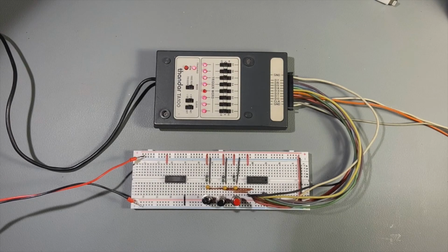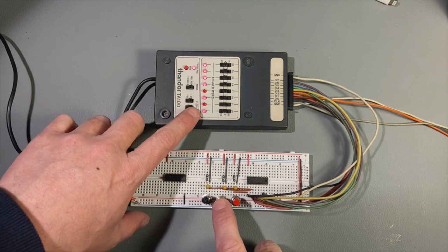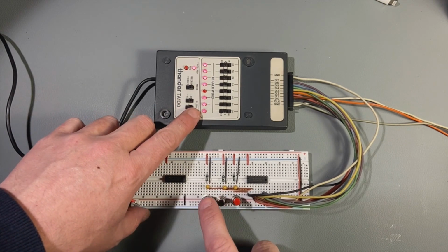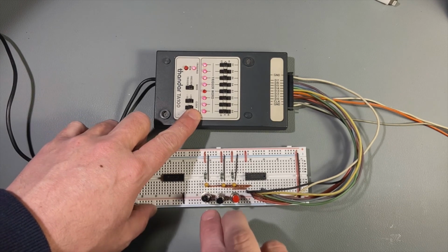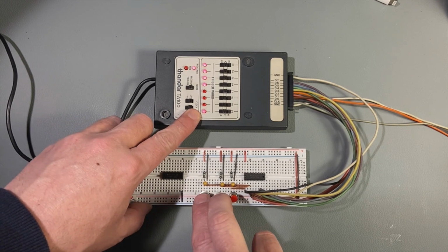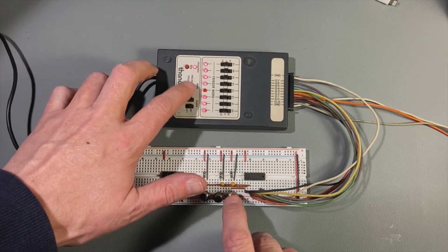We can see that the LEDs D4 to D7 of the logic analyzer are high. You may remember that I mentioned that the outputs for these devices are active low. You will also notice that the enable pin is also high. We can see this on D0. When we change the inputs from high to low, we can see these change in the logic analyzer, but nothing will change on the output because the enable pin is not active.